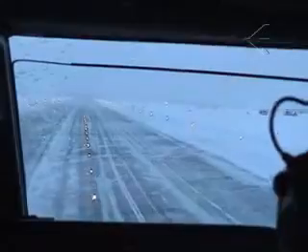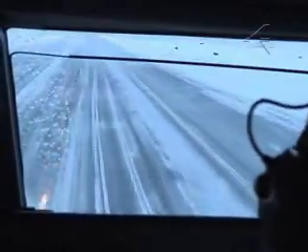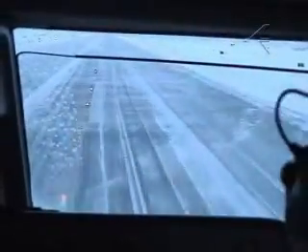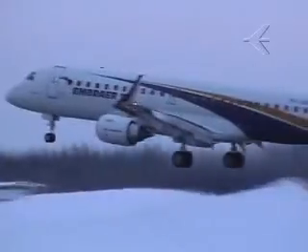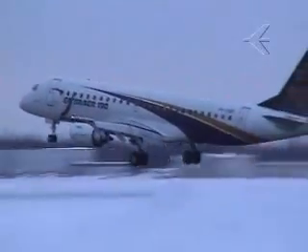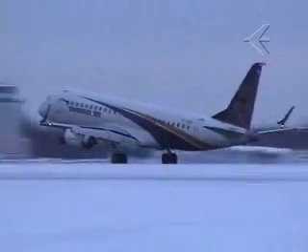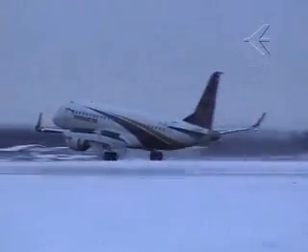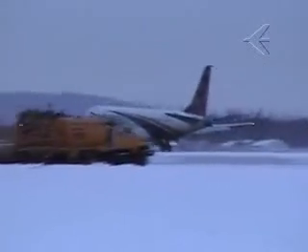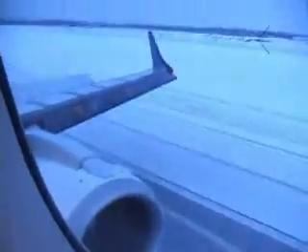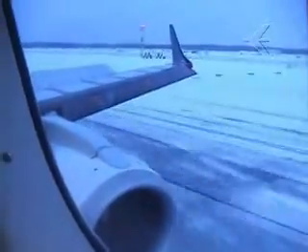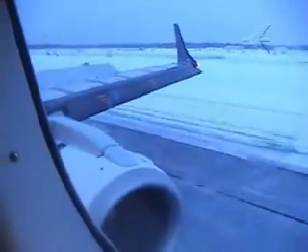It tends to favor a firm touchdown over touching softly, which is quite reasonable, mainly when landing on contaminated runways. The flare is fine-tuned so that it should not be a hard landing, with no floats nor bouncing. Nose gear should also land at an average rate. Touchdown should happen at approximately VREF, and your landing distance will be consistent with that.